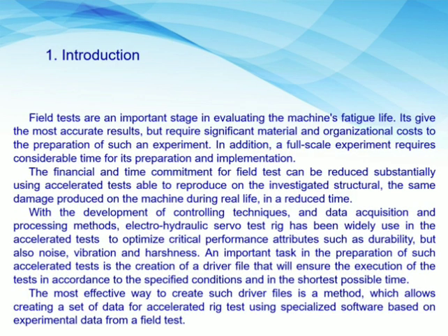Field tests are an important stage in evaluating a machine's fatigue life. It gives the most accurate results, but requires significant material and organizational costs for the preparation of such an experiment. In addition, a full-scale experiment requires considerable time for its preparation and implementation. The financial and time commitment for field tests can be reduced substantially using accelerated tests able to reproduce on the investigated structure the same damage produced on the machine during real life in a reduced time.